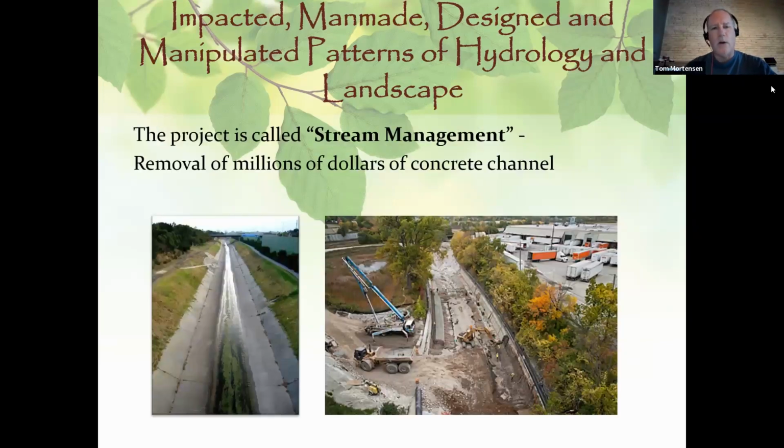So here in the Milwaukee area, all of the streams and tributaries in the 50s and 60s were channelized with concrete. And that was well intentioned. There was a lot of, we're going to be more efficient. We're going to prevent flooding on adjacent lands. We're going to create more developable land. But it had unintended consequences downstream, because the velocity of water that moved through these systems was uncontrollable. It picked up more and more velocity as it went down closer to the river.